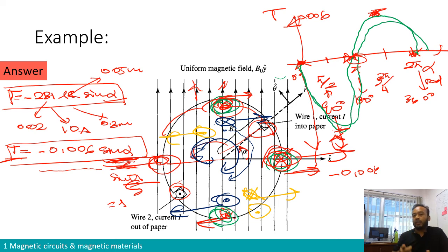So we know now that in order to rotate a machine, we can produce a force by carrying a current inside a conductor on a rotor. So this is one method. To calculate the force, we use Lorentz force law, which is the vector product of magnetic field and current that produce the force. And then, of course, in order to calculate the torque, you need to project the force on the tangential direction of the rotor. So that's what we have been doing.